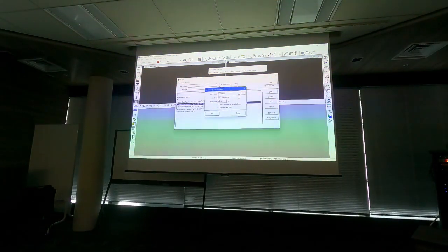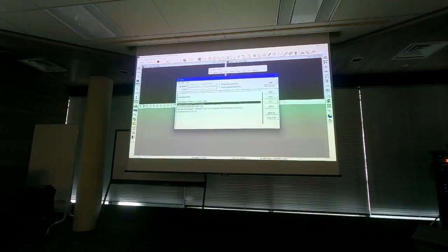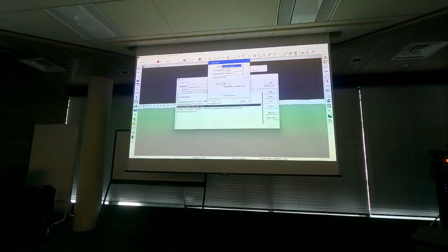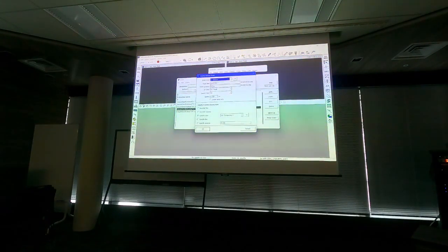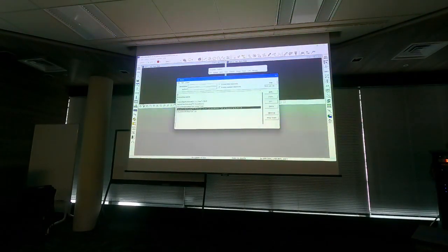If I have higher altitude data, I may make the tolerance setting bigger, and in the smoothen, the same kind of a change, and perhaps in here radius, because my data is not so high density, and then I would have a macro which I can run on the project for a big aircraft data set and do the same sort of smoothing logic.